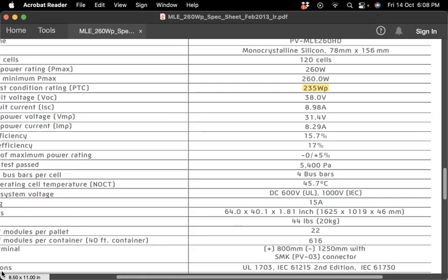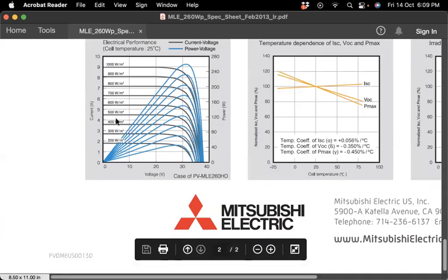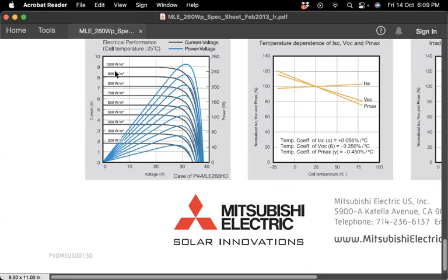So you can easily find these parameters here, considering the different irradiance levels. The higher the irradiance, the higher the current, up to what we call the one sun condition, which represents the typical standard condition for a solar cell. As I previously mentioned, whenever you go into real measurements, your sun intensity may exceed this 1000 watt per meter square.